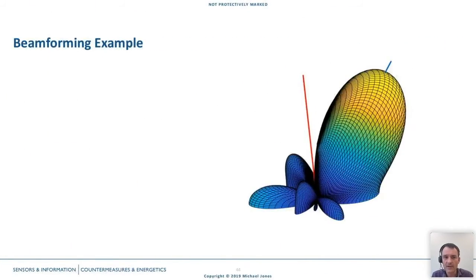What does beamforming look like? Well, it looks something like this. So again, we've got our jammer, in this case, is that red line. So we're still nulling out that jammer in a very powerful way. But we've also, where that blue line is, that's the direction of arrival of a satellite. So we're steering lots of antenna gain in that direction. And that's a really, really powerful technique that's been used for many years by the military and is becoming more available again to critical infrastructure.